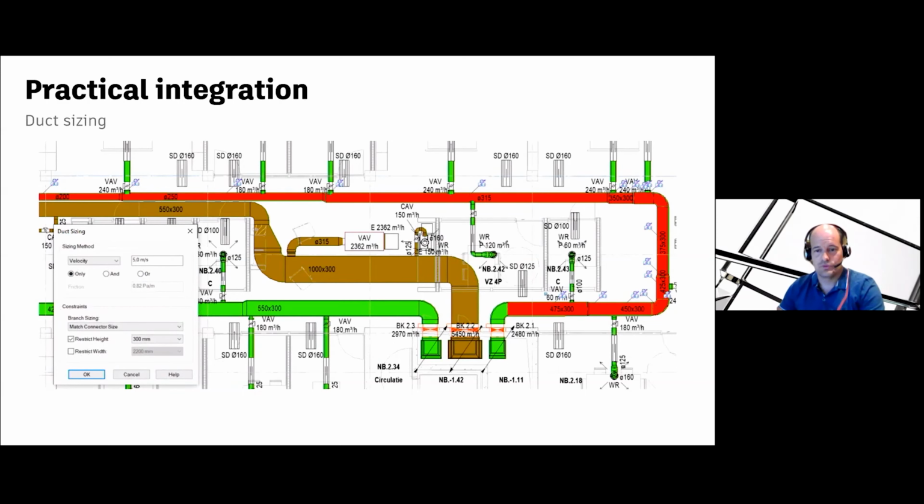This is what it looks like in Revit then. Here you see, I will quickly show my pointer. What's indicated in red here is a piece of duct sections that I selected with the trick that I said earlier. I just click on this one, then I hover over this one and press Tab, and then I click again, and then all those ducts in between get selected. Those are the main ducts in a lowered ceiling.